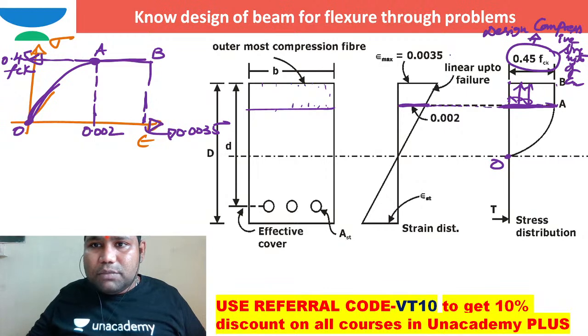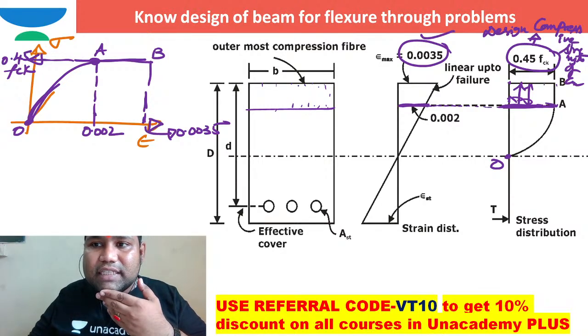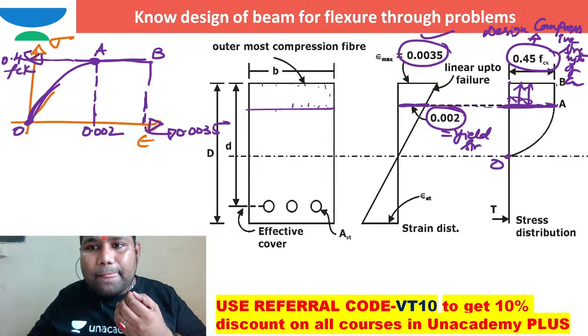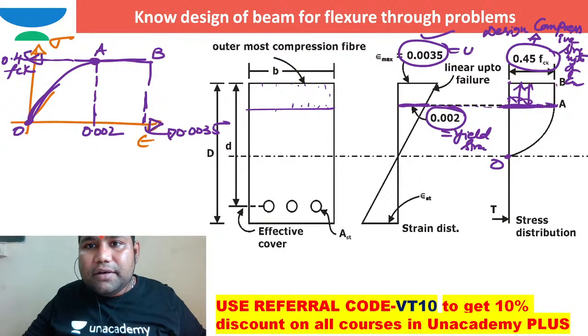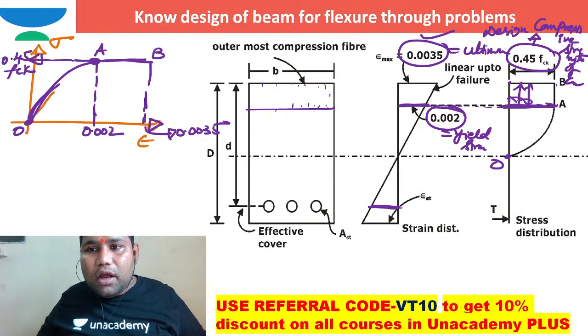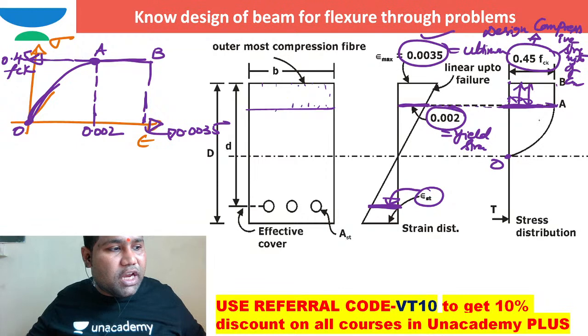And why we got this 0.0035, this is answered. The strain at the point where there is a change between rectangular variation and parabolic variation is 0.002, this is the yield strain. This is the ultimate strain, right? I just need to mention epsilon st here, and I had mentioned even the shapes of this.